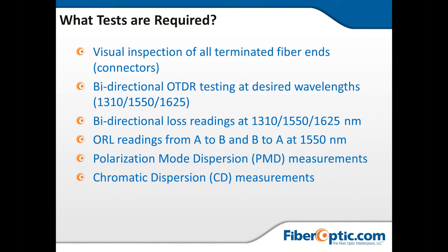As I said, I've traveled the world, and I have been to parts of the world to troubleshoot problems that were solved with a cartridge cleaner and a quick click connector cleaner, a bulkhead connector cleaner. It's amazing how a little bit of contamination on a connector end will kill your entire link. So I cannot stress strongly enough the importance of cleaning and doing a visual inspection to verify the quality of your connector ends.